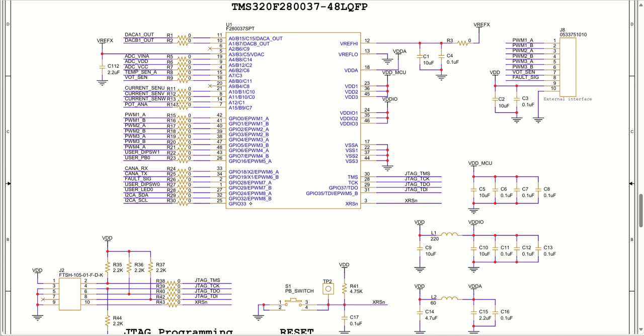In this microcontroller system, you can see we have proper pin configuration for the analog side. We have voltage monitoring of 15 volt, 3.3 volt and 5 volt. Then we have temperature sensor monitoring separately, and temperature sensor monitoring from the IPM. We have current sense for U phase, V phase, W phase. Then we have one potentiometer connection. We have a DAC output here.